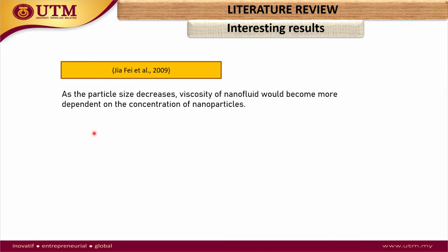So there are some interesting results from literature. So let's look at Jiafei's work in 2009. As the particle size decreases, viscosity of nanofluid will become more dependent on the concentration of nanoparticles. So in the study, they compared nanofluid with different sizes of nanoparticles, which is less than 20 nanometer and more than 20 nanometer. So with nanoparticles of less than 20 nanometers, they observed that the viscosity of nanofluid mainly depend on the concentration of nanoparticles.